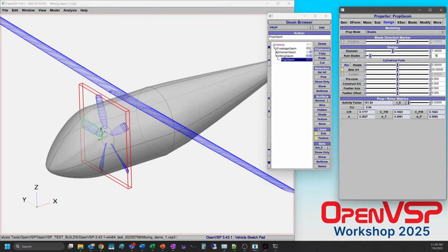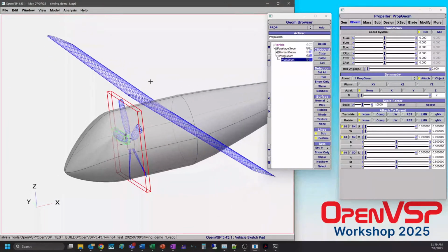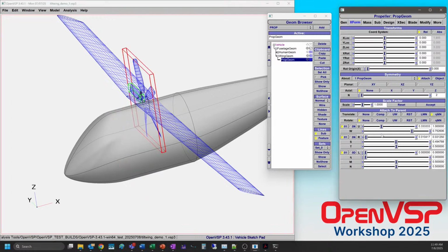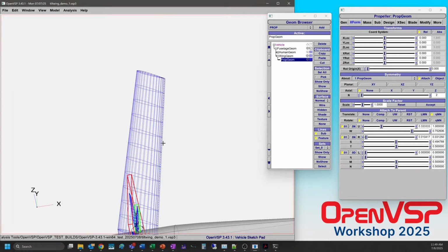So for our propeller, instead of attaching in component, what we really want to do is attach it to a certain position on the wing. Now we can do this a number of different ways. There are other presentations where we talk about attachment and rotation with parent and child in the ground school. For here, we're probably just going to set this to something like eta. So now, down here, we can set this as a function of essentially the span or the semi-span.